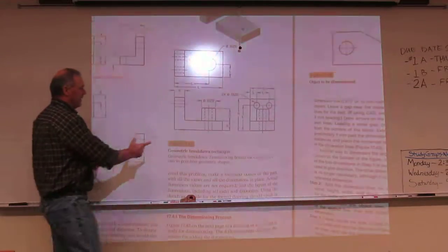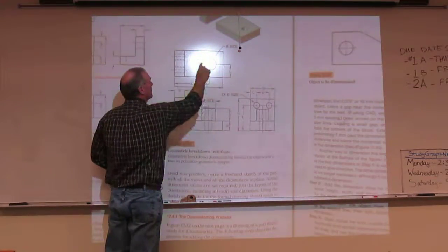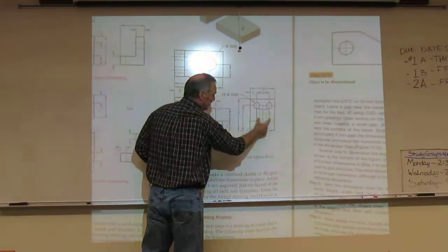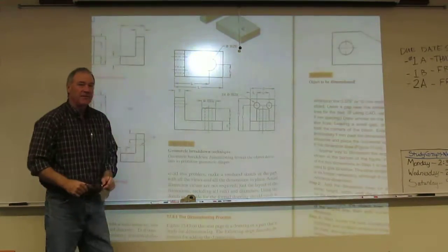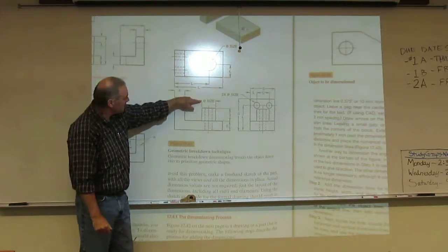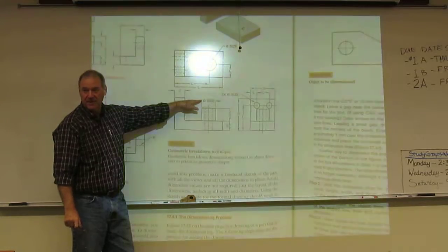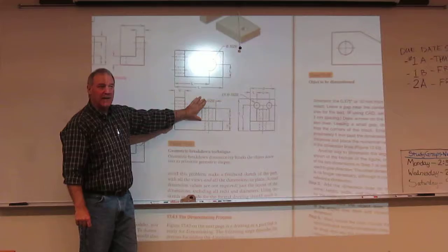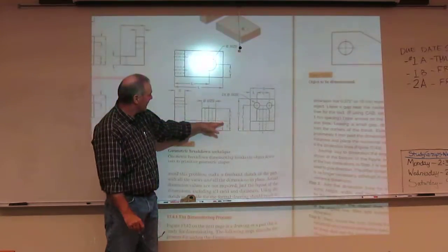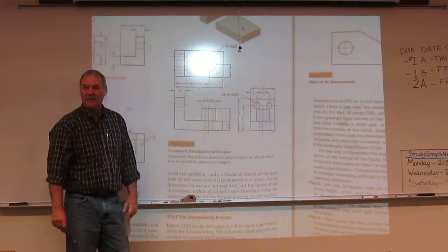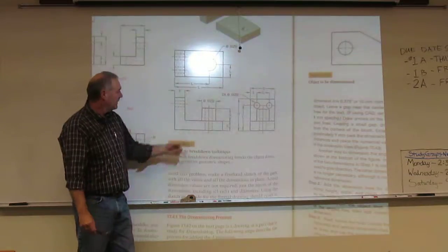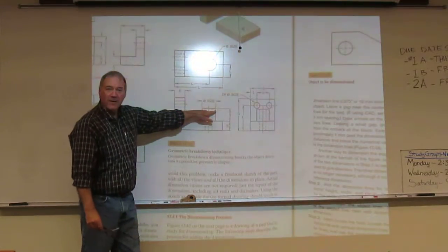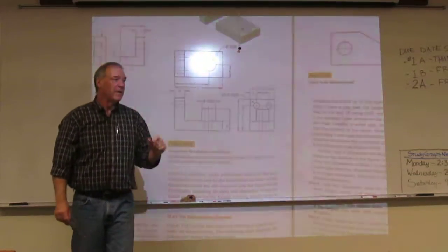But here's my positive cylinder right here, here, and here. It has been chosen to put the size in this location because here's where I see the real profile of it. And due to grouping, we also get the height of it located. So we know all the information about it. So here's where I put the size on positive cylinders.